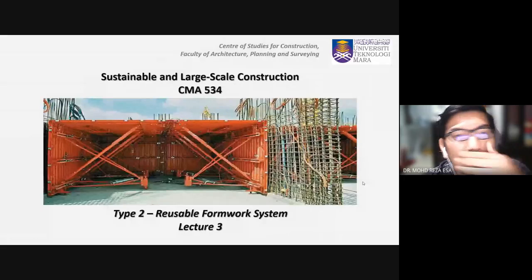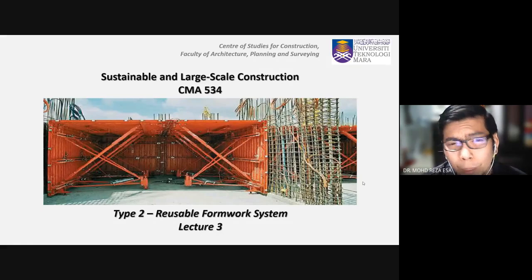We looked at the components that can be made as precast components, which include precast column, precast beam, precast slab, and some of the volumetric or what we call modular construction or 3D construction components, which include the house unit. It can be done either in full unit or semi-unit, for example, the toilet unit, shelter, and etc.